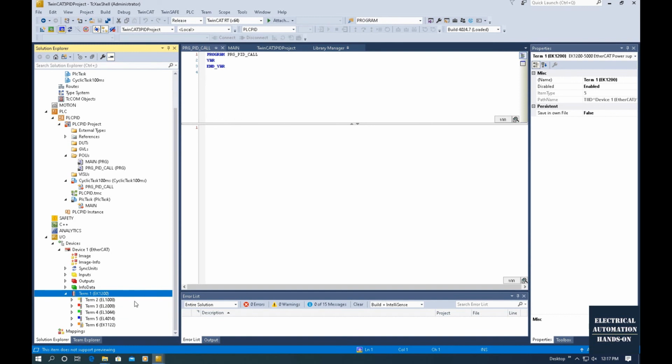So this is just a basic demonstration of how we can configure the hardware of the TwinCAT I/O systems. And you will see there's no CPU configuration here. That's because in the Beckhoff style, the controller is one system, a WinCE or Windows system, and that is one PC system. And the configuration of the controller is at the top of this project tree.